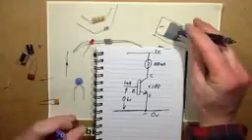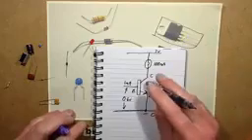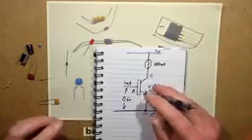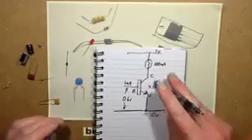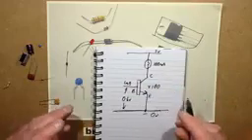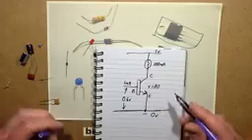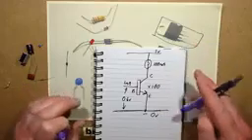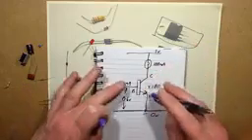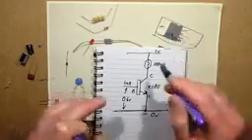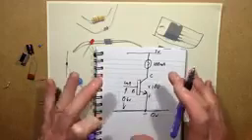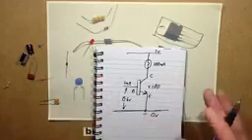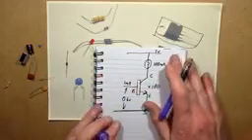You also get a hybrid. The MOSFETs are not as robust as the traditional, let's see, bipolar transistor like this one. So you get a hybrid called an IGBT, an insulated gate bipolar transistor, which is almost like a traditional transistor with sort of low gain, but with one of these transistors on the front of it. So it's very easy to turn on. It can switch massive currents, and it's really a robust transistor. But you can find all that online if you actually look for it. This is just a basic guide.